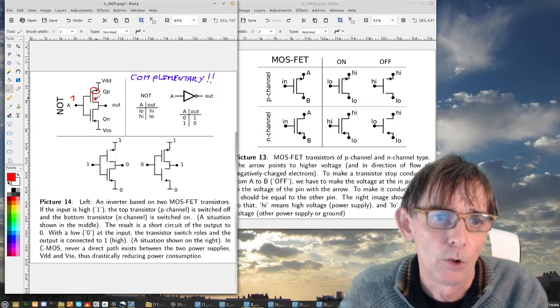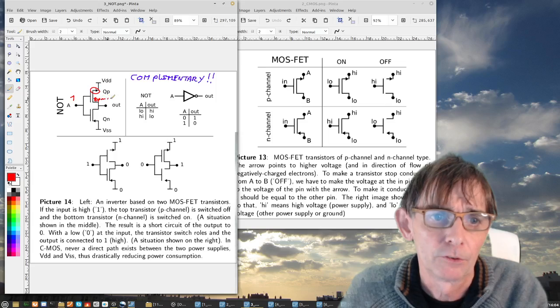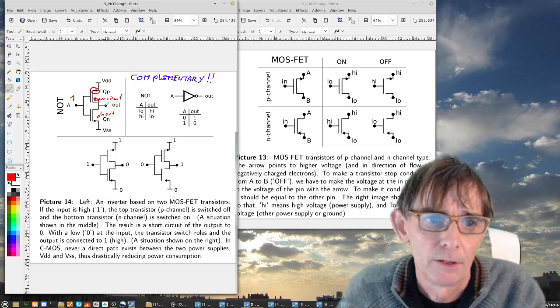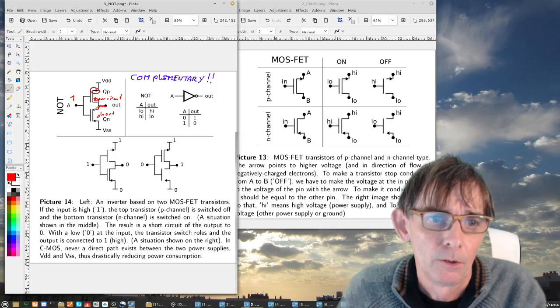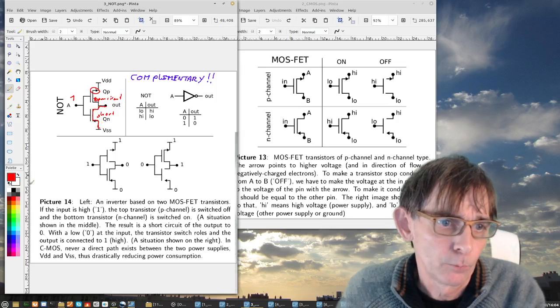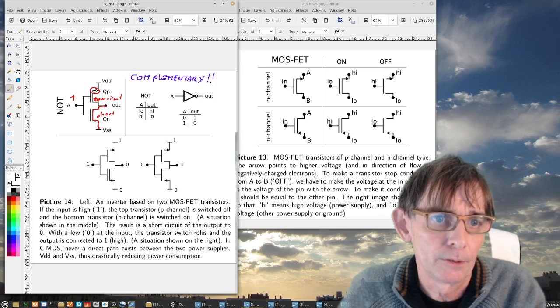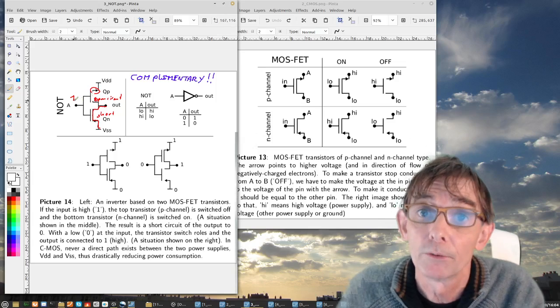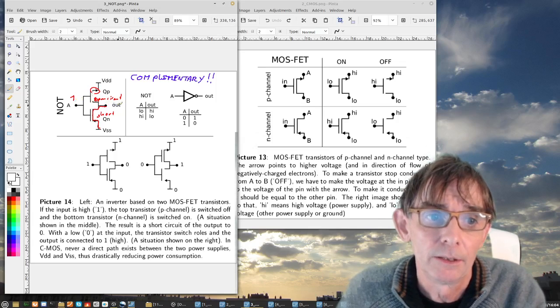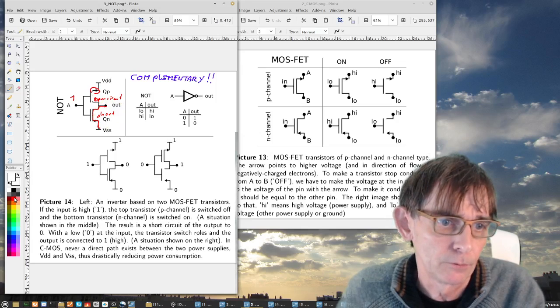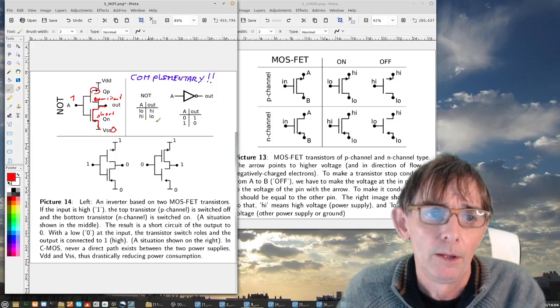This one is open circuit, and this one is shorted, meaning now we have a conduction path from here to here. And the other one, I can show it here, is actually disconnected. So as you can see, if we put 1 on the input, the output is shorted to ground, and this ground, of course, we will call 0.